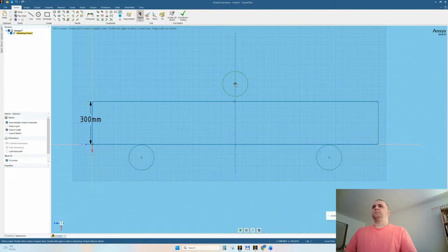So let me move this. I didn't constrain this axis. Can I somehow lock it? We have vertical constraint. Do we have fixed constraint? Horizontal? Fixed constraint, yes. On this axis, all right. So also on this axis, maybe something like this. Because I like to pull this circle, all right, and it doesn't move the axis. This is enough from my side, in my opinion. Let's go with what we have.